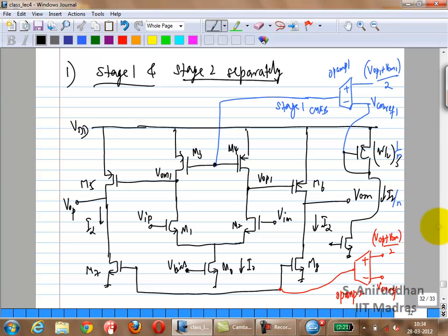Let's go back to this picture. Have we missed out anything else? Two important things we have missed out. Well, they're the same. Compensation. So where all do you need compensation? Gate and drain of M5 and M6. What is this compensation for? This is just dominant pole compensation for your regular op-amp, differential op-amp behavior. That is just your overall op-amp. And of course, I have not shown it here, you can also have RC, RCCC here, zero cancellation, pole zero cancellation.